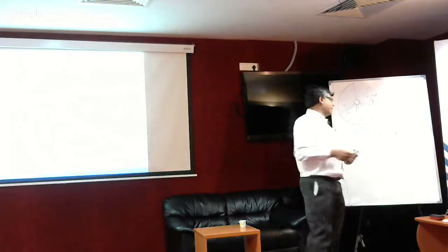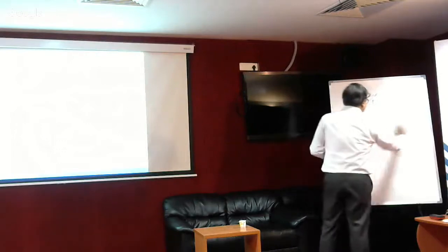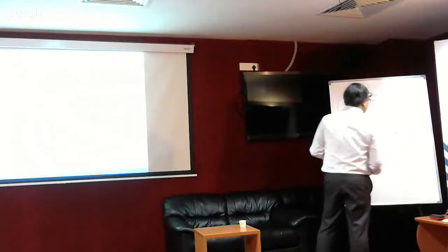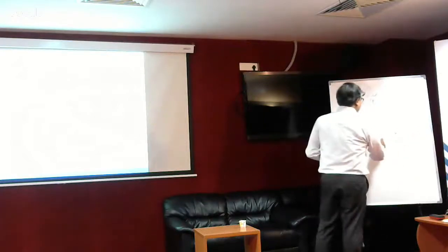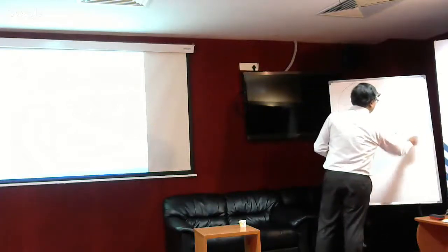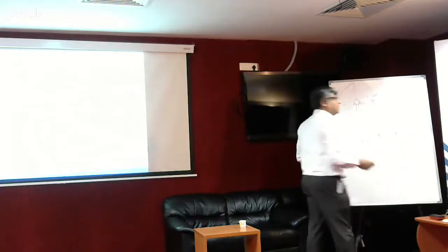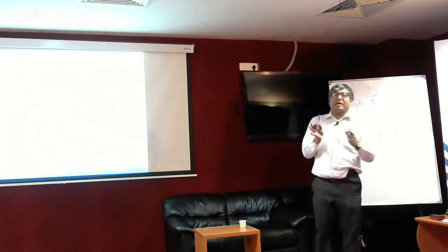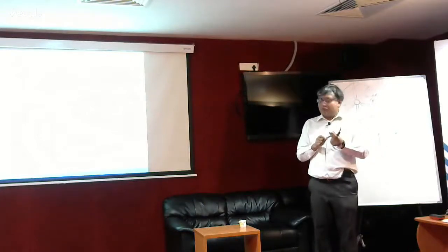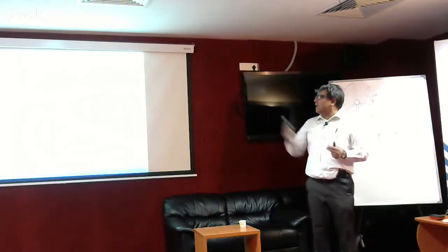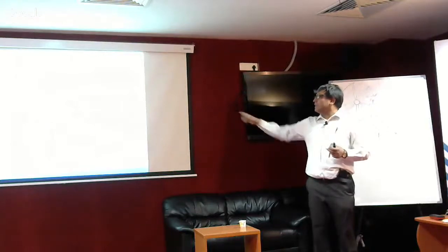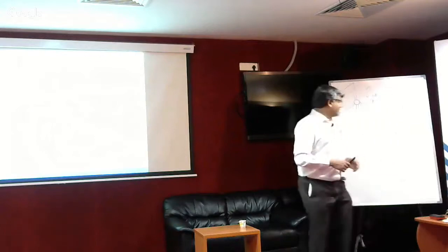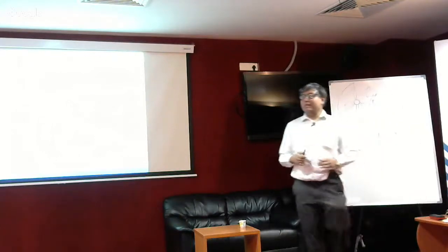So we assume that whatever wind is blowing is effectively responsible for the creation of the structures here. And therefore, from here to here, it's moving with a speed equal to the mean wind speed, because the mean contains everything sort of averaged out. So if I take the mean wind speed and multiply by the integral time scale, then we get a length scale corresponding to the length scale of the eddy.